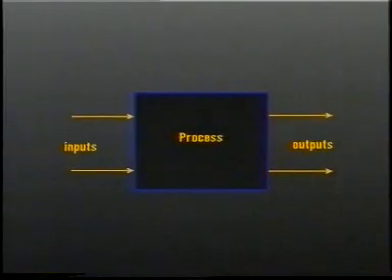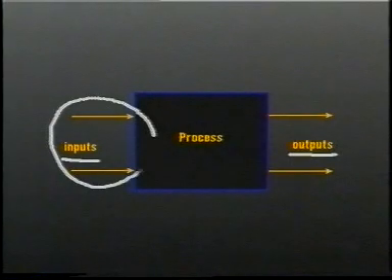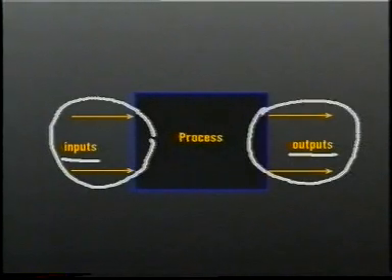The variables that influence the status or condition of a process are called inputs. The variables which change as a result of changes in the process inputs are the process outputs. Obviously, if we can identify all the important inputs and outputs that affect a process, it makes it much easier to understand the way the process works. In order to keep the analysis of a process as simple as possible, only the inputs and outputs which can be measured or controlled should be considered as part of the final process control solution.